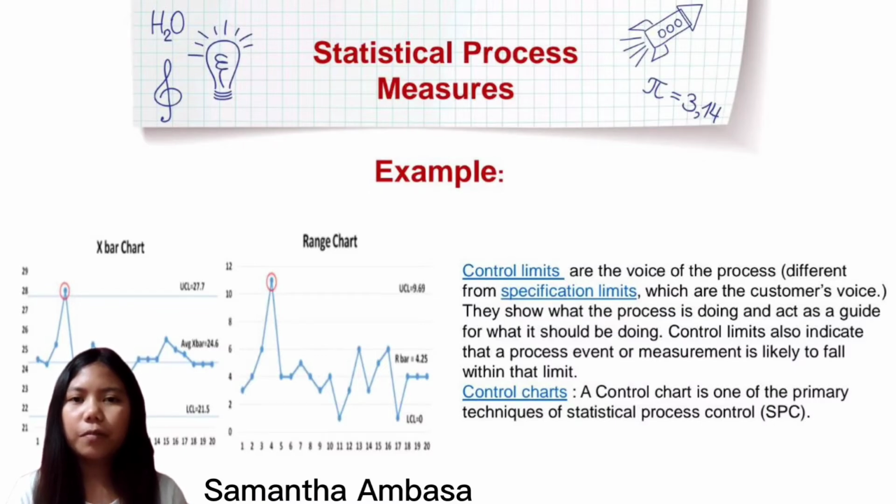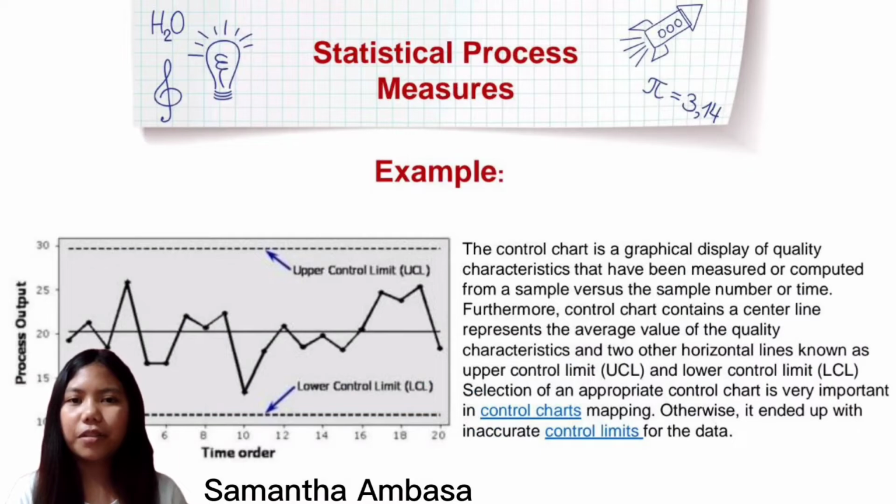4. Develop a subgroup strategy and sampling plan. Determine the subgroup size based on the product criticality and determine the sampling size and frequency. For example, collect 20 sets of plate thicknesses in time sequence with a subgroup size of 4.